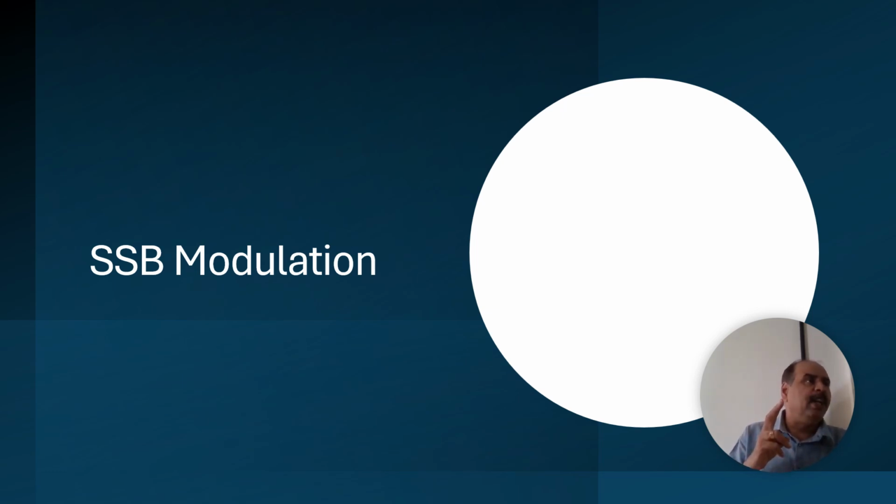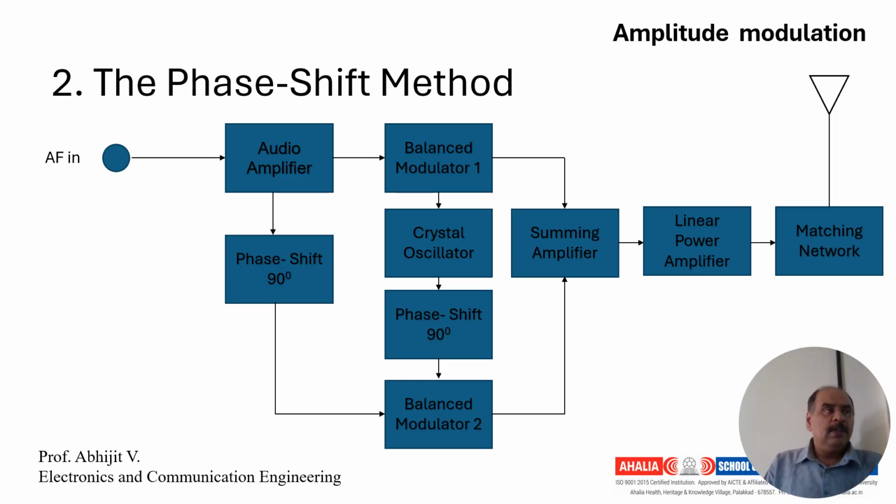Okay, in this class we will be dealing with the second method, that is the phase shift method. So this is the basic block diagram for phase shift method. We have an audio input, we have the audio input amplifier, then we are passing it through a balance modulator and then to a crystal oscillator. Now here you are mixing the signal with the carrier signal. After that you are creating a phase shift and then this particular signal is further amplified.